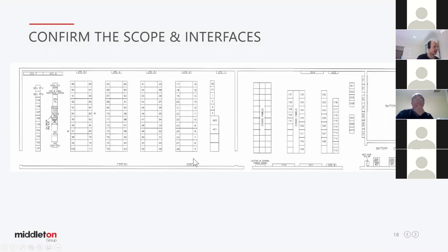So straight away we've got to recognize, okay, where are the existing field cables marshaled for this location? Are they in CTC A? Are they in CTC 2? Will there be a changeover? Are there any signals which we need to keep as part of the existing arrangement? For example, there might be an on-load tap changer scheme. There might be another scheme that we may need to interface to for the transformer, like an auto close scheme. There are various things that we need to consider for that. I might just move on to the next slide.